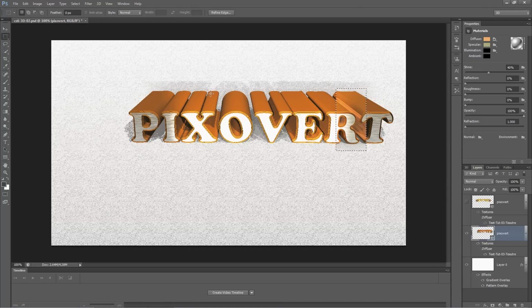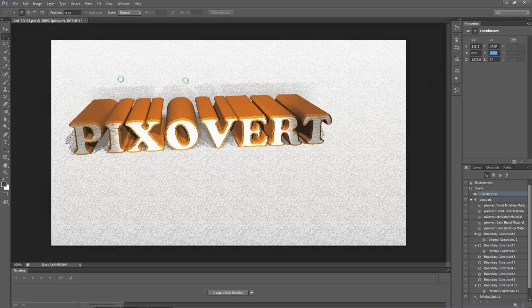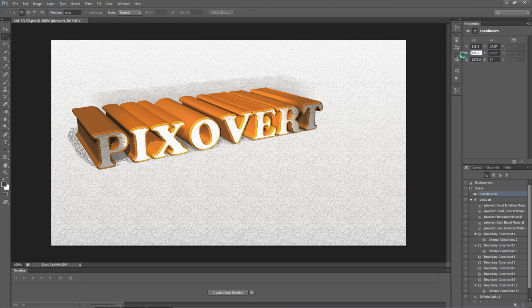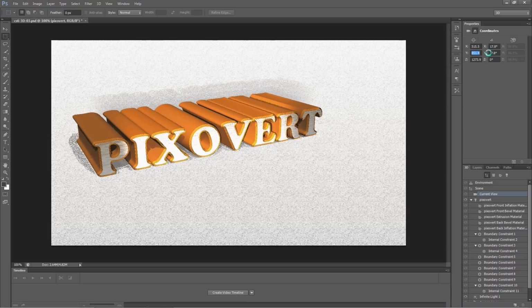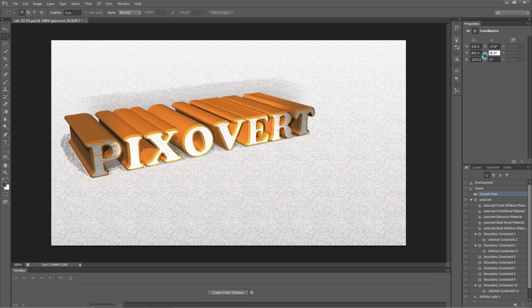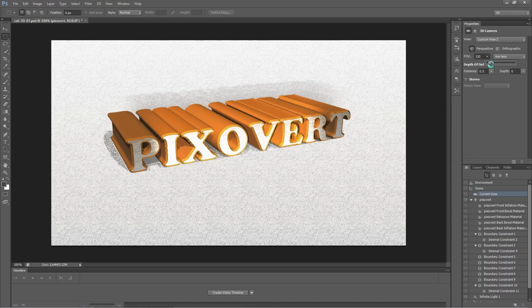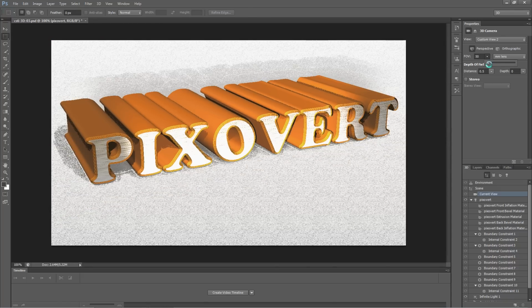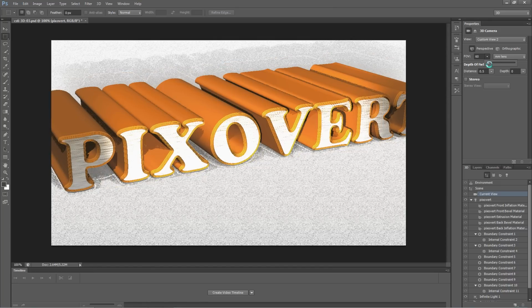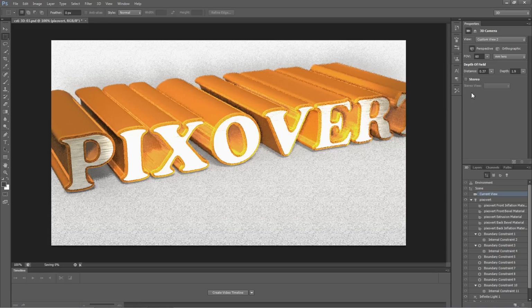What I want to do now is to reposition the image so that we can get a kind of depth of field effect using the camera. I've selected the current view camera in the 3D panel, and I selected the coordinates button in the properties, and within the properties I'm just making a few adjustments to reposition the camera. Okay, back to the main camera properties. In the FOV tab I'm going to change the lens to around 50 millimeters, maybe 60 millimeters, and what I also want to do is to change the distance and depth. Okay, just to save some time, I've started the render. I ended up with a distance of 0.37 and a depth of 1.9.